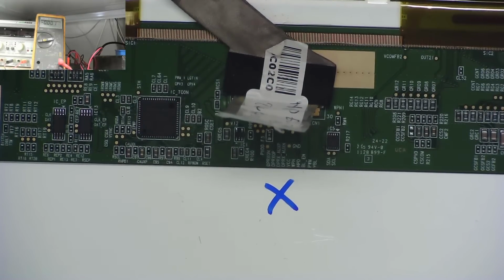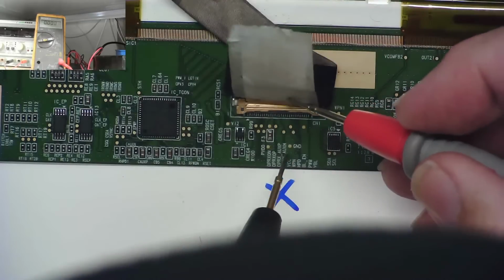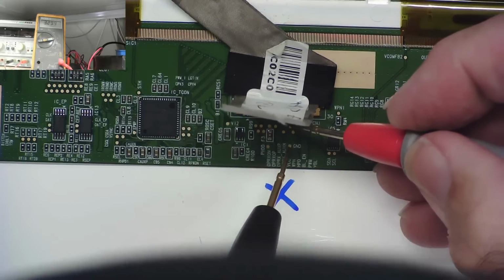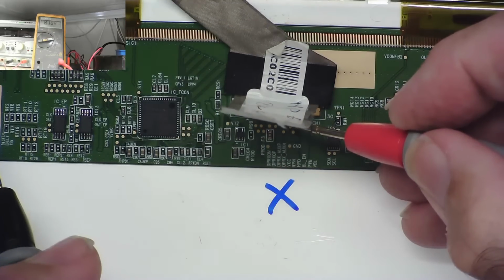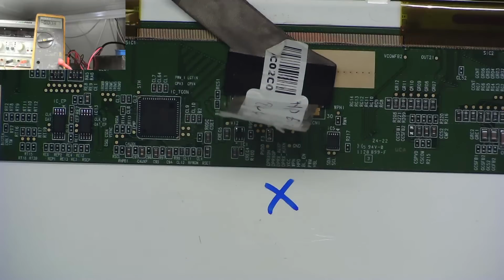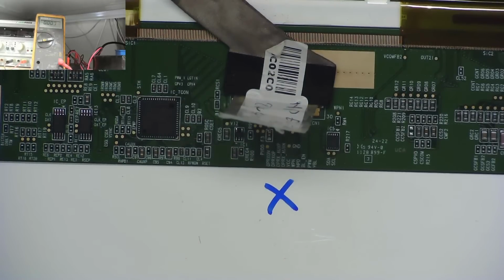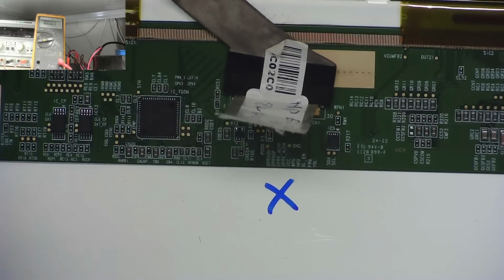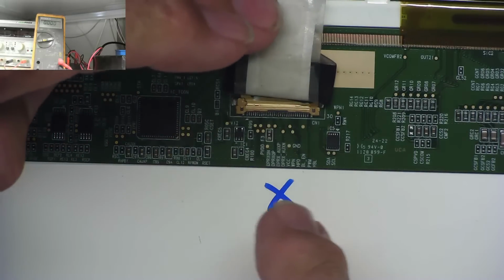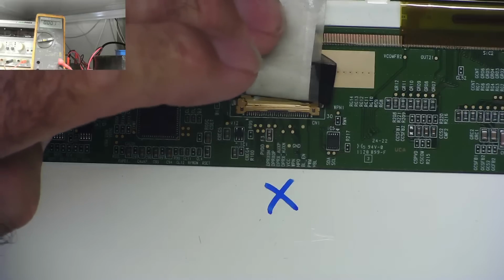PWM. Next one, BLEN. This is Backlight Enable. I'm expecting this to be 3 volts or 5 volts, some sort of voltage. Let's go on the ground again. Yeah, 3.3. I'm just moving my meter, so that's a ground point. That's the easier one. Okay, so Backlight Enable, yeah, 3.3. That sounds sensible. If that was active low, so the enable is when it's 0, BLEN would normally have a line across the top of it, or an asterisk or a hash in front of it.